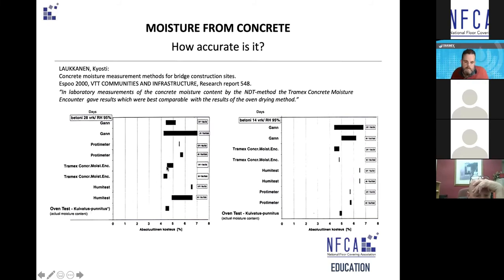If you're using a meter to measure the moisture, you have to treat it a little bit like the calcium chloride test, where you prepare the concrete, you make sure it's bare, you make sure you're testing in the same condition that you'll be installing the floor. If you do that, it gives you a very good moisture content gauge. It's a very good meter for that.